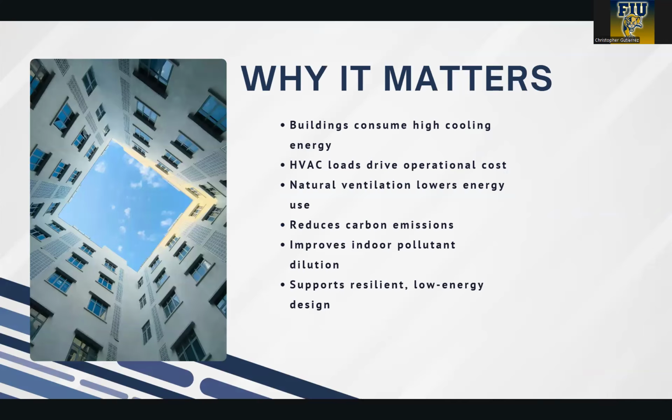So why does this matter? Cooling loads take a large share of building energy use. So HVAC systems are responsible for most of the operating costs in many climates. Natural ventilation lowers energy use and cuts carbon emissions. It also improves indoor pollutant dilution by increasing outdoor air exchange. As energy prices rise and comfort requirements grow, reducing mechanical cooling loads becomes more important. Natural ventilation supports that when applied correctly.